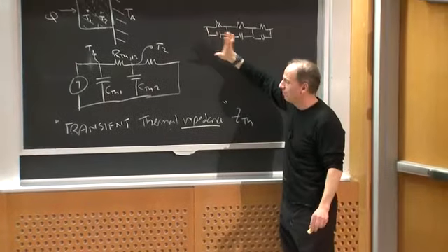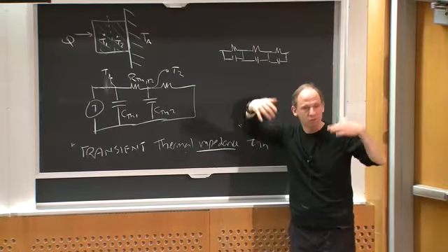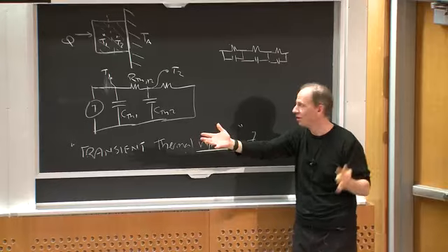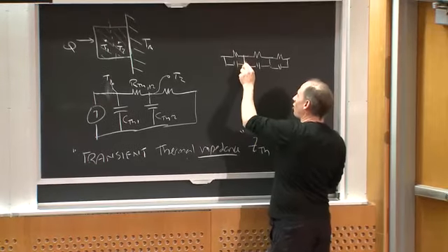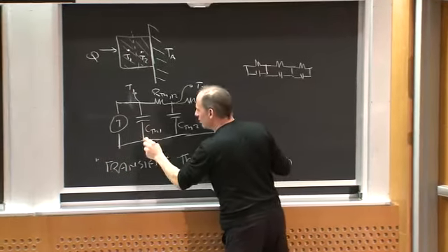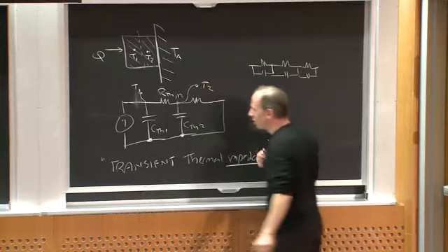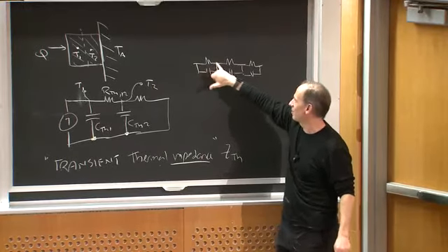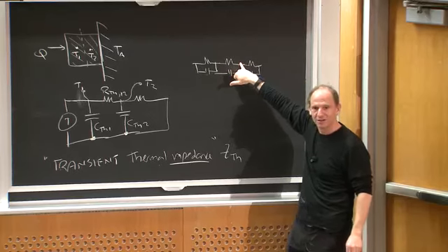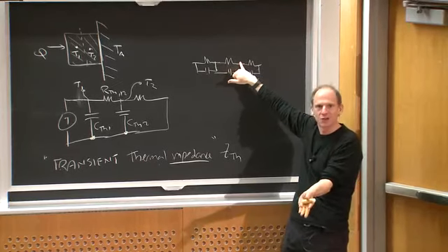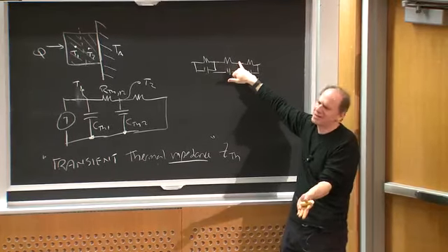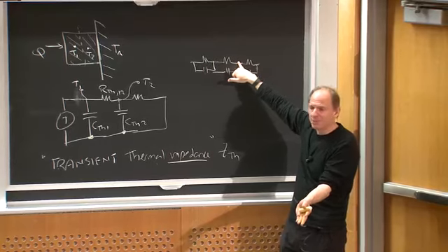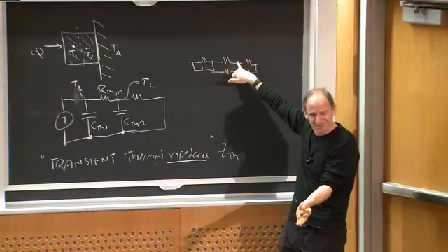You can kind of try to take this kind of model and map it over to that kind of model, but any real thermal capacitance, if you're going to represent Fourier heat transfer, thermal capacitances ought to always be down to, we can use ambient, but it should always technically be absolute zero. These are referencing the thermal capacitance to other places in the thermal path where the temperature is changing, all right? So it's basically just not right, but people do it because it's convenient.